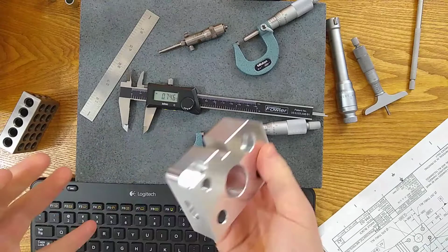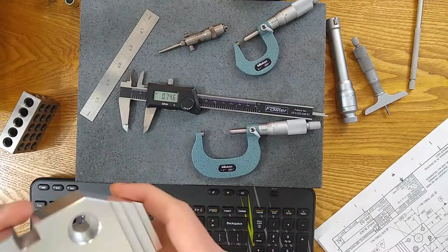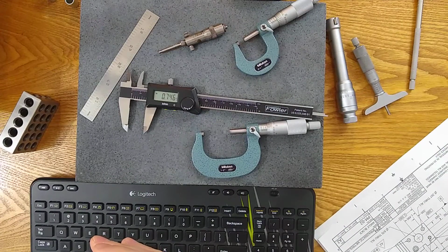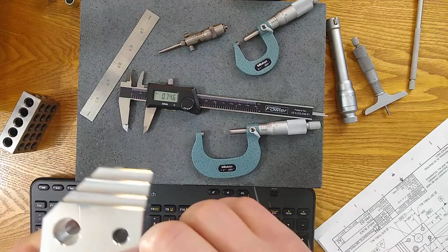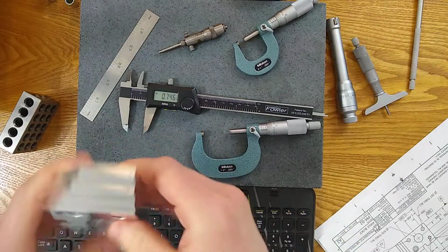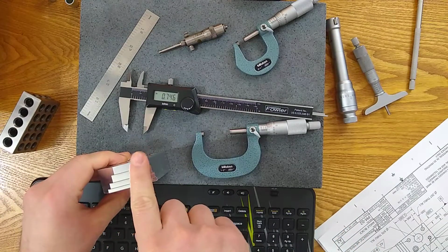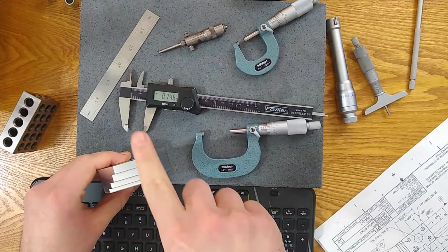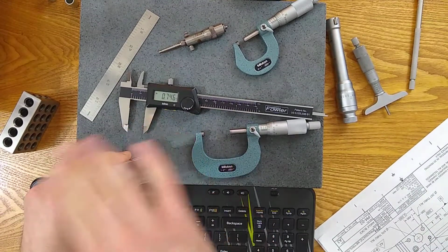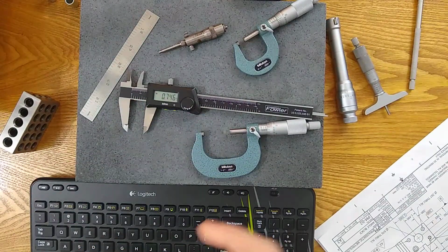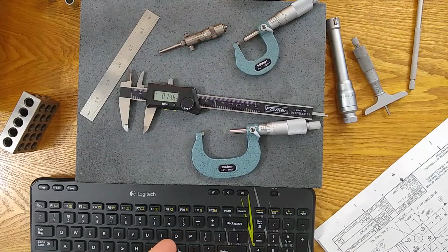So imperfections in the part itself can lead you to make certainly something's wrong, but you may not find it. And other times you may find it's in, that tapered surface I just used. You might find that it's in because where you measured it, it was in, but other places it's not, because you didn't measure every single point. So consider those.